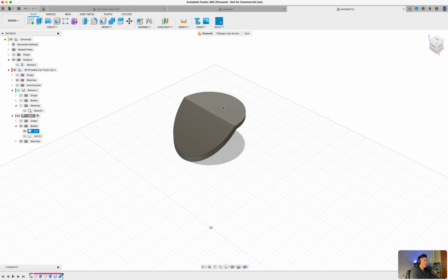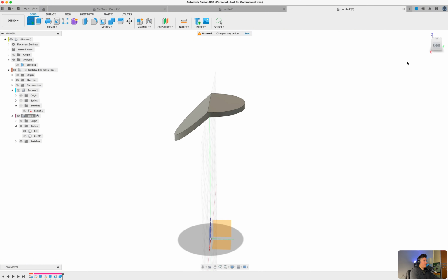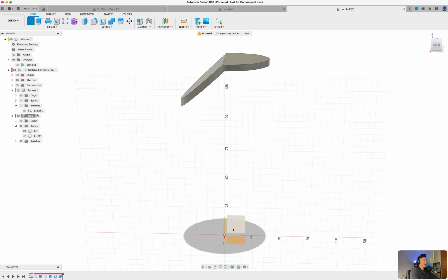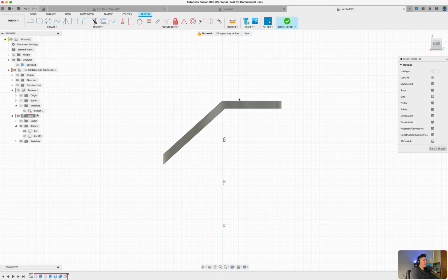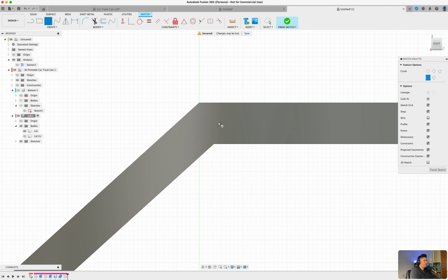Now by pressing create sketch, what we want to do is select this right view. So if you were to toggle your home view, and look to the very right of this, we're going to toggle this plane here. After that, let's go ahead and create some sketches. Now, as of right now, we're actually not sketching on any particular face or body. What we really want to do is just free sketch in this environment, and I'll show you exactly why in just a second. So by using the center diameter circle tool, let's select that, create one circle, create one more circle, and create one last circle.